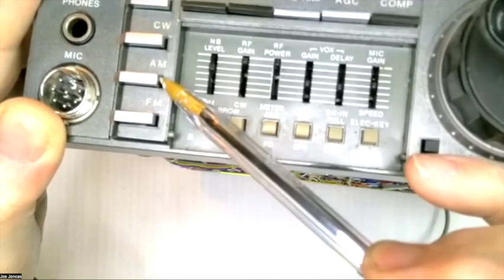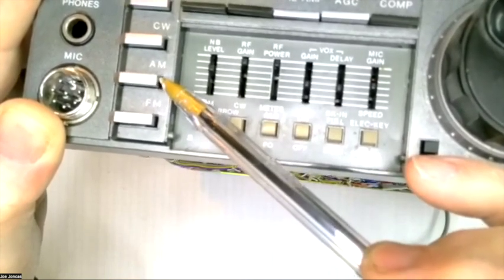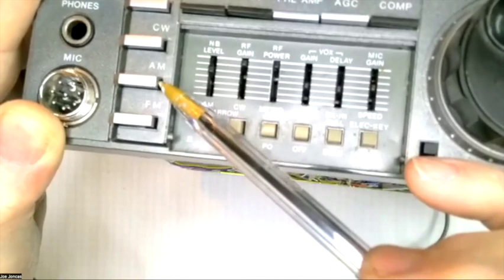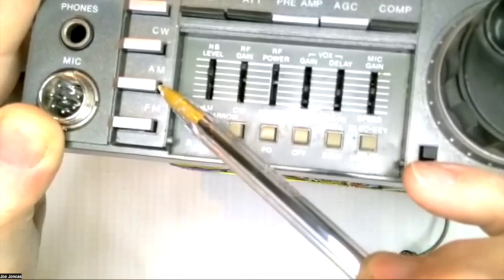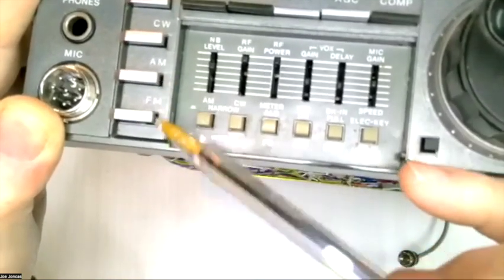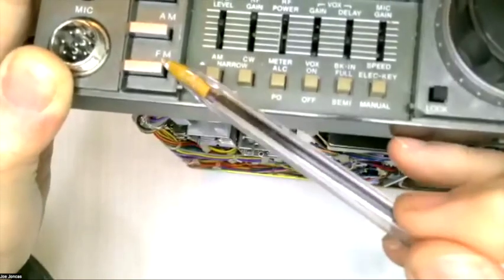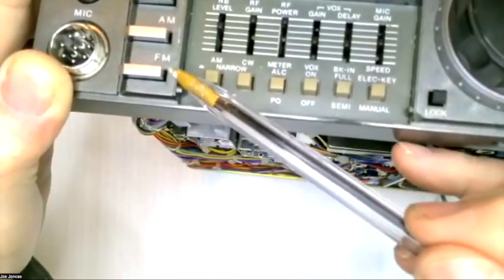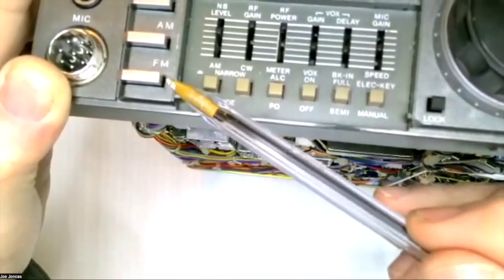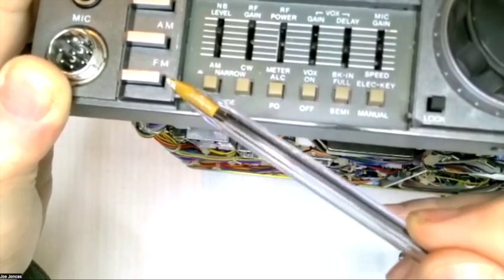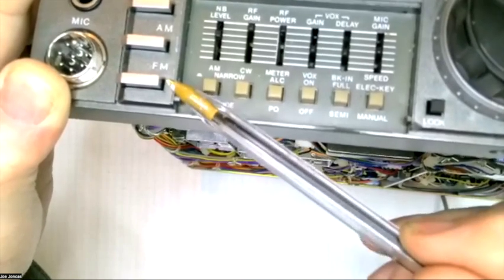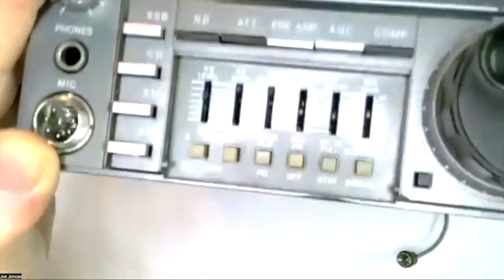When you amplitude modulate it, the peaks go up higher from the carrier, so the radio will not handle the extra voltage. So you have to lower the AM power. And then this is FM, which is probably the toughest mode because it puts out a constant carrier and you change the frequency rather than the amplitude of the signal to get your talking across.